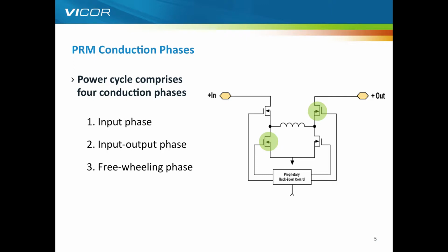There's a freewheeling phase where we've got Q2 and Q3, and then we have a clamp phase. The clamp is responsible for limiting the amount of negative current that we have in the switching cycle as we pass through zero, and you'll see again in more detail. It's important to note that we do cross the 0 point or return to zero in each of the universal cycles. Therefore, this is a discontinuous mode device as distinct from continuous mode converters.